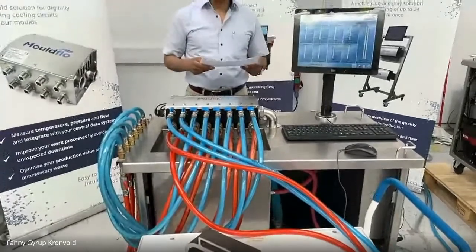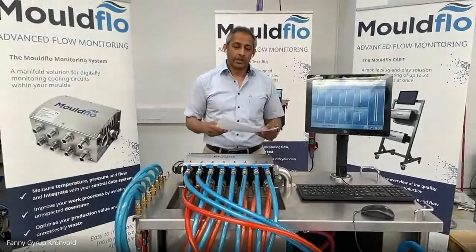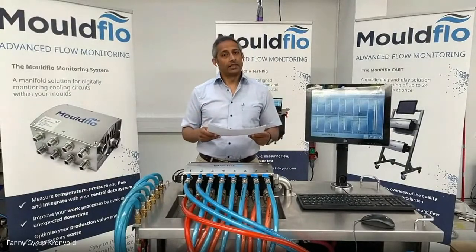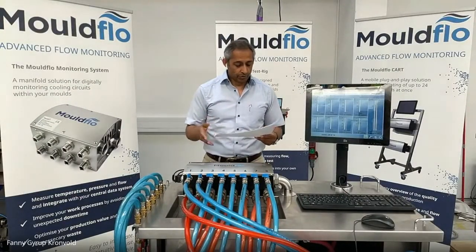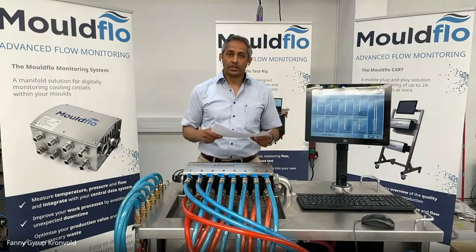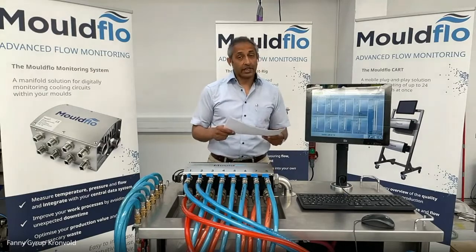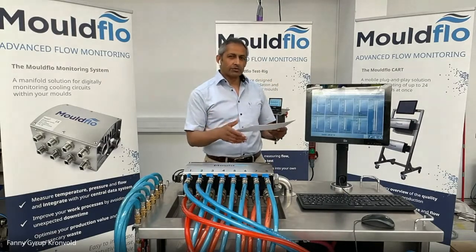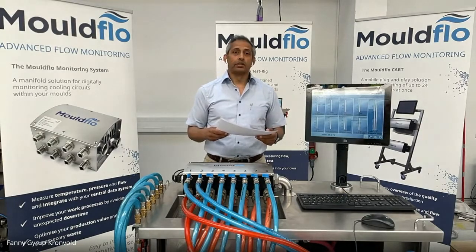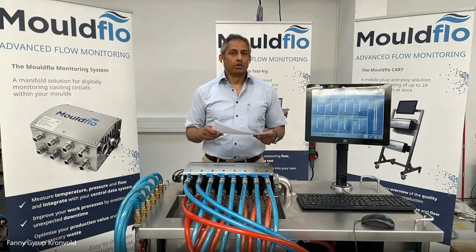As explained in the first webinar, the Test-Rig is designed with the purpose to check and verify if a mould's cooling channels are performing according to calculation and design. The purpose of the Test-Rig is to check if the mould cooling channels are damaged or blocked because of rust and scale, etc. And also with this Test-Rig, it is possible to do an extended test, where you can find the optimal flow rate by applying the minimum water pressure.